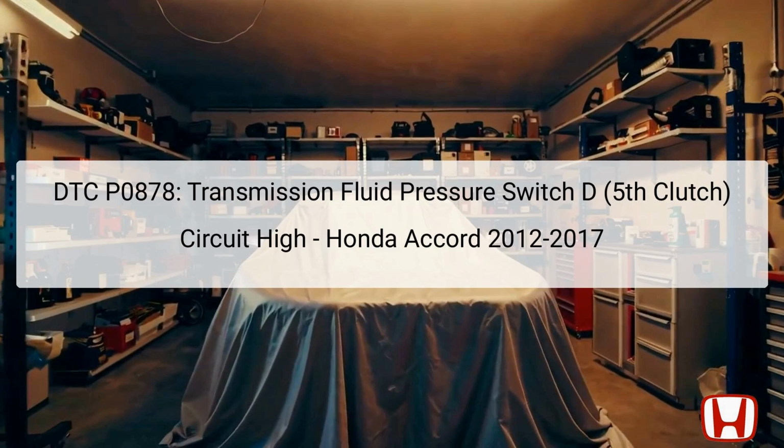The Diagnostic Trouble Code, DTC P0878, indicates an issue with the transmission fluid pressure switch D, which is associated with the fifth clutch in Honda Accord models manufactured between 2012 and 2017. This switch is a crucial component that monitors the hydraulic pressure in the transmission, specifically related to the operation of the fifth clutch. When the vehicle is in motion and the fifth gear is engaged, this switch should indicate whether hydraulic pressure is being supplied.